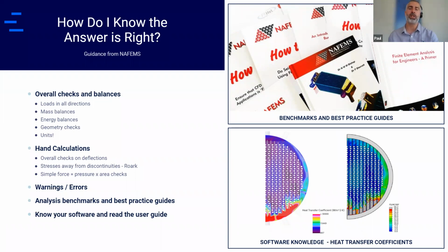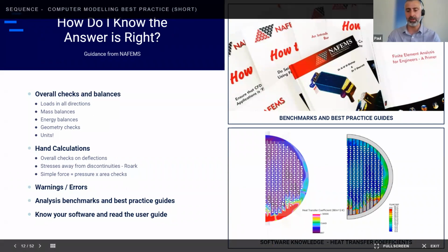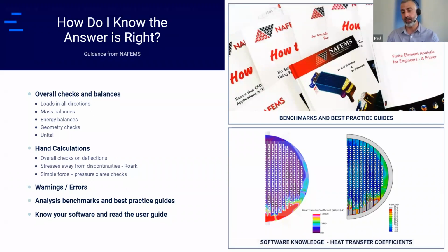There's a way of exporting them, which gives you a local heat transfer coefficient and a local reference temperature as a field. So you can use both of those values. You can have a relevant boundary condition that you could use in an FEA software. So this example here on the right is just showing a tube sheet. We've got a heat transfer coefficient I've calculated.